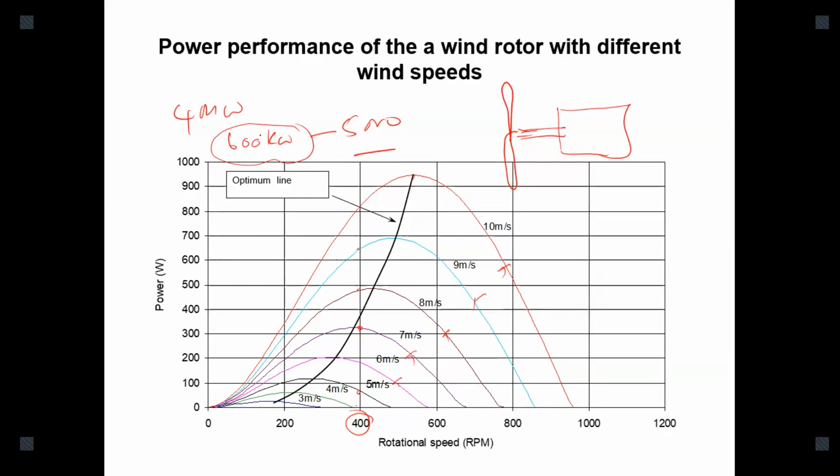These are constant RPM machines. I think the true term is fixed RPM, however, we are calling them constant RPM machines. At that time, it was that way. These wind turbines worked in a similar way. Only at one wind speed can they harness the maximum possible energy. At all other points they work at low efficiency. We will discuss these things later very clearly.